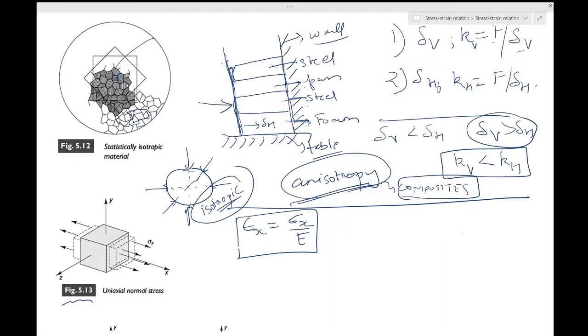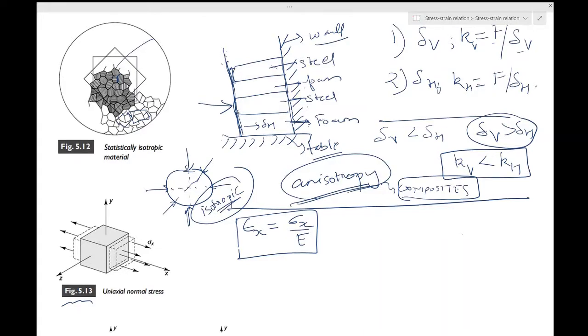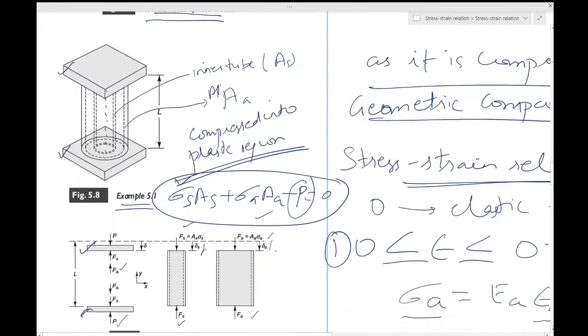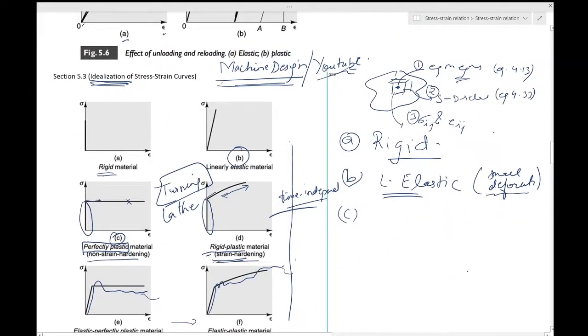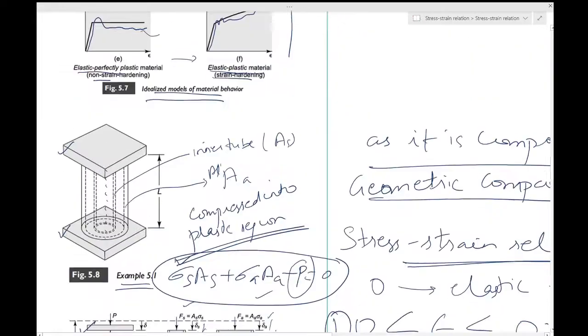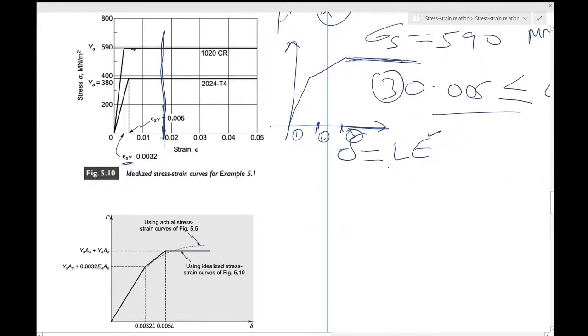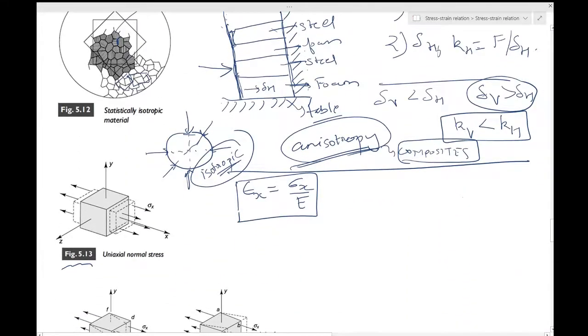And the modulus of elasticity E is numerically equal to the slope of the line in 5.7b. So if you go along over here, the slope of this is E. Not the angle, sorry, this angle, if you want to denote it, would be tan inverse E. So that is what a linear elastic isotropic solid is, and you have considered only one component of stress right now.